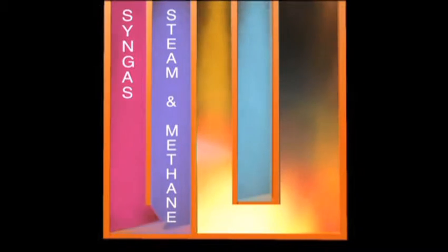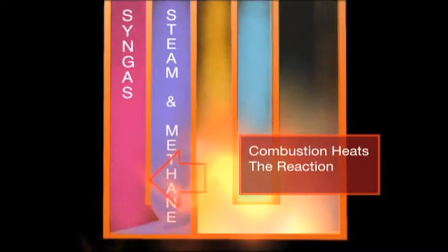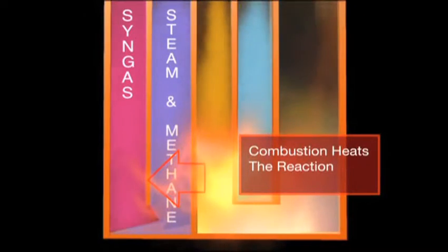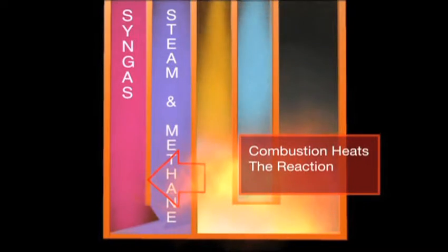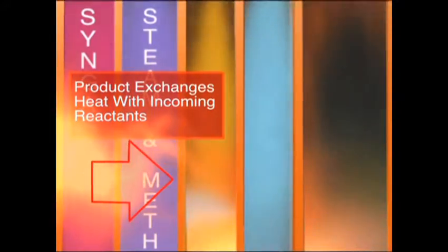The exhaust stream makes a U-turn and exits at the top of the reactor. Heat from combustion is used to drive the equilibrium-limited steam methane reforming reaction, which is most effective at temperatures above 850 degrees Celsius. In the process channels, steam and methane are converted into synthesis gas or syngas, which consists primarily of hydrogen and carbon monoxide.